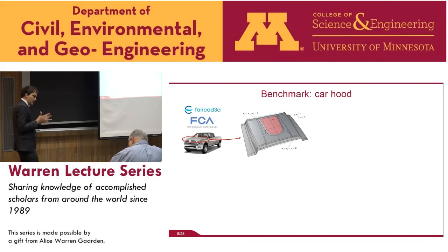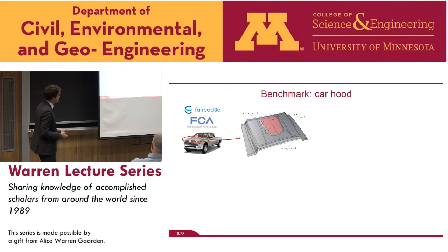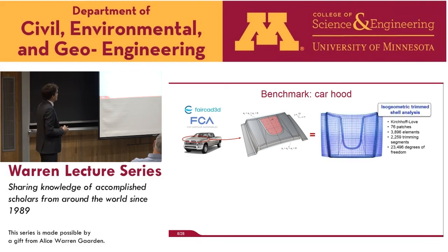And then with our method, we are directly able to do analysis. There's no meshing, no geometry cleanup. We use our trimmed shell analysis directly operating on these spline elements. These are the spline patches, basically, the individual surfaces. These are the underlying surface elements. And we are leveraging the trim data structure in terms of trimming curves and topological relations to correctly deal with connecting trimming lines and integrating over cut elements.